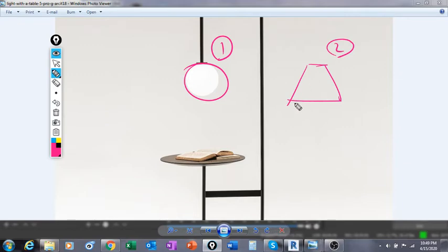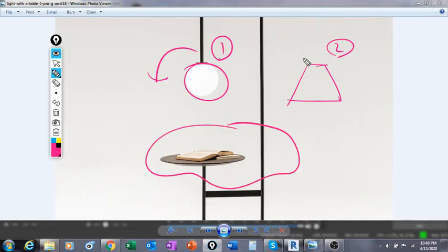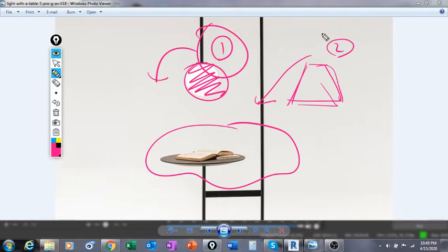How are we going to do this? Well, for this, we're going to have to create two separate families, okay? And we're going to have to actually create what we call visibility parameters, and then insert this family inside this existing family we are working on. And we're going to see how we can configure the parameters. So if I want, I can have a spherical, like a ball lighting fixture, or I have a cone one, okay? So basically we're going to create these two as separate families.